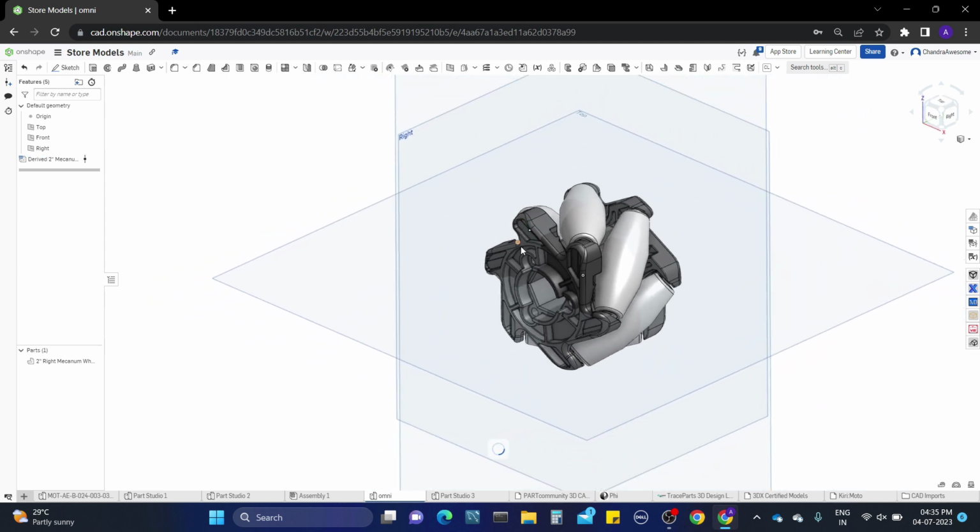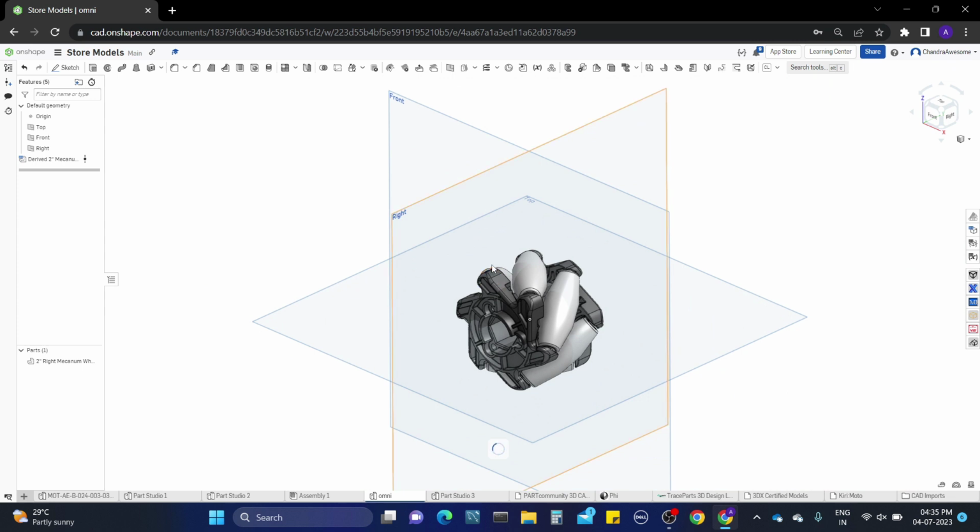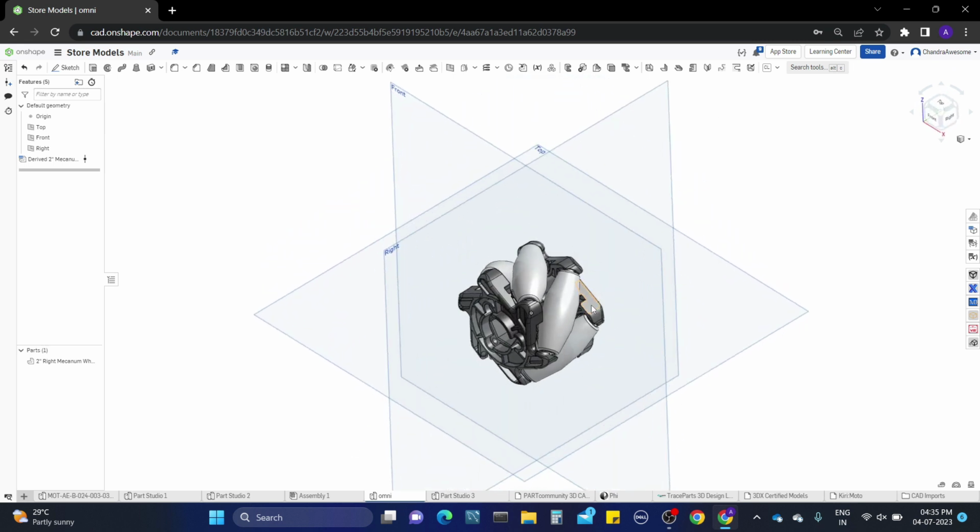Okay, now let's start the model. We need four wheels, but we got one wheel. What we can do is click on the part and use the transform tool, because I want to do the mirror operation that will make it easy for us to model. I'm going to use translate by XYZ, and move the part in the Y direction by some distance, about -3 inches.